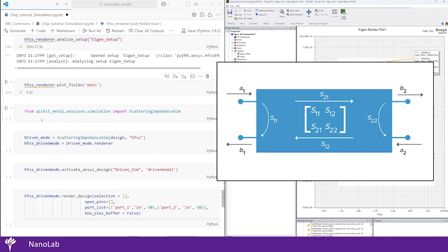S-parameters, or scattering parameters, describe how microwave signals travel through and interact with a circuit. S11, or reflection, shows how much of the signal sent into port 1 reflects back. S21, or transmission, shows how much of the signal sent into port 1 passes through to port 2. S12 and S22 describe transmission or reflection in the opposite direction, or at the second port. These values are expressed as ratios of outgoing to incoming wave amplitudes, usually in dB.